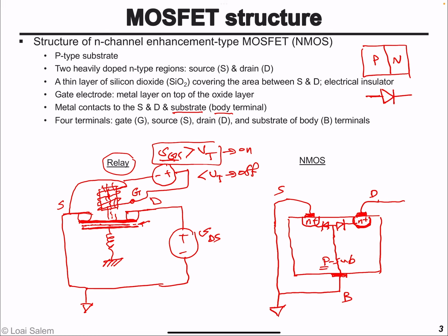And then let's apply a voltage difference between the drain and source. Let's call it VDS, say it's like half a volt, 1 volt, something like that. So in this position, since this terminal, which is the P terminal, is essentially equal to the source, this diode is shorted, or essentially, yeah, you can remove it. Now, when we apply voltage difference between the drain and source terminal, as you can see, you have a reverse bias diode. Essentially, if we look at the equivalent circuit,